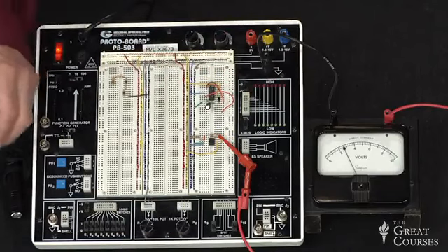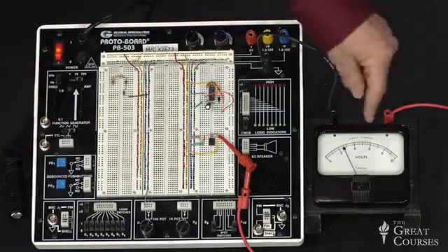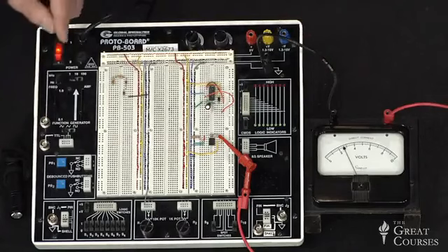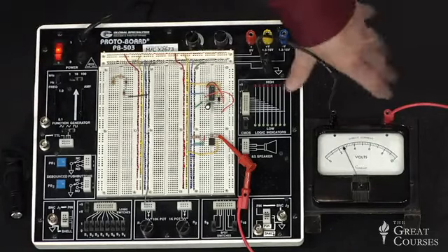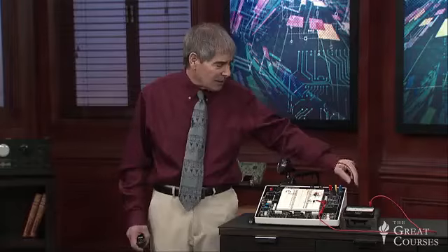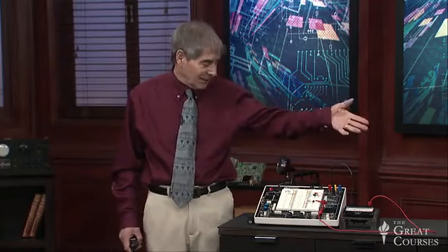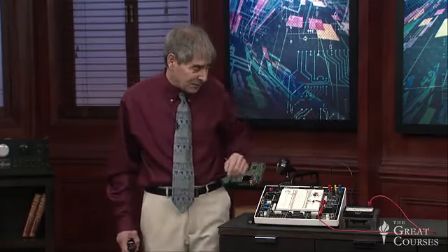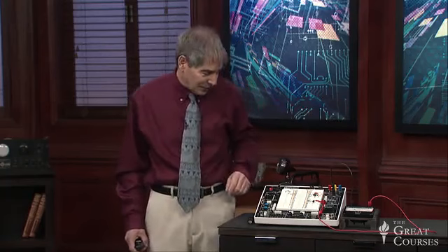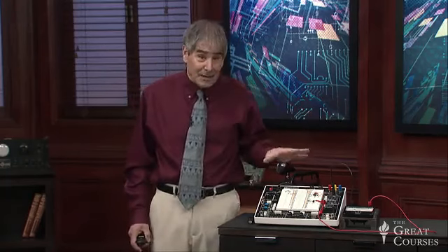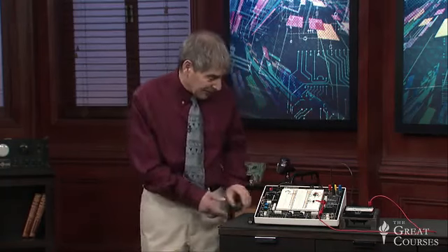The other difference is, because this voltmeter reads only positive, well, I could have switched the leads, but that would have looked confusing. So because it reads positive, I've actually turned the phototransistor around, so it's going the other way. I've connected the emitter at the top, and I've connected that to minus 15 volts, in fact, and I've connected a resistor to limit the current, so the phototransistor doesn't get too much current through it. But it's basically the same circuit I've just shown you. And let's take a look.